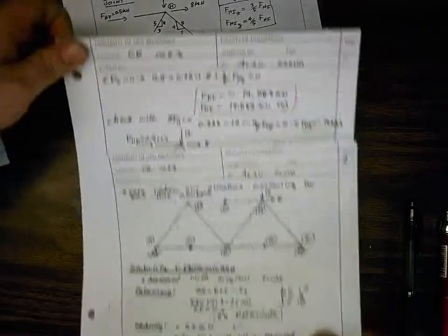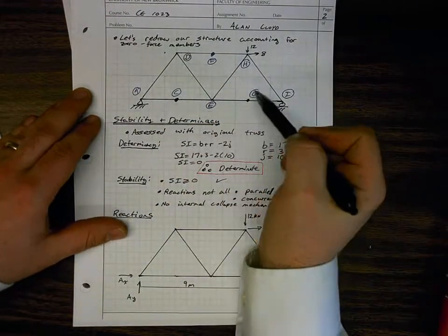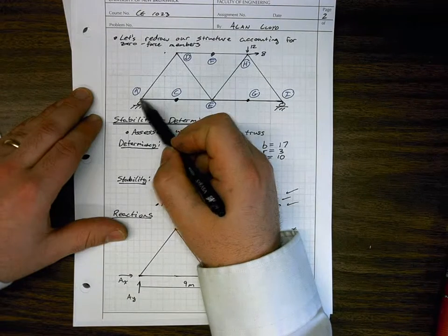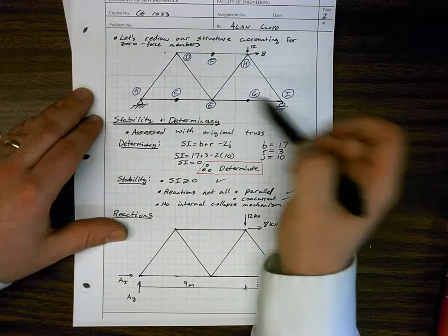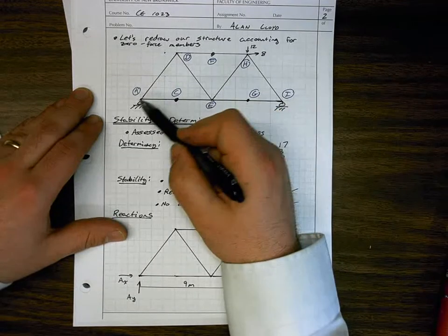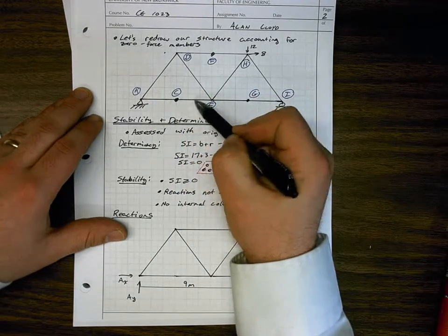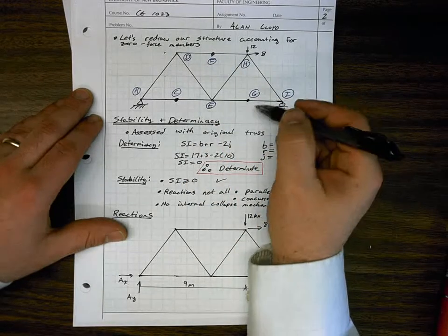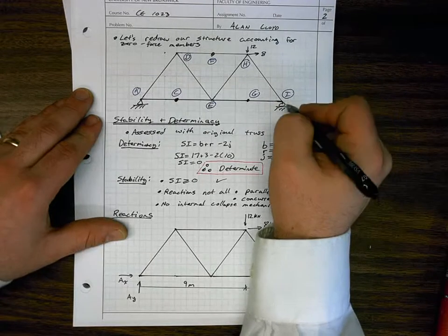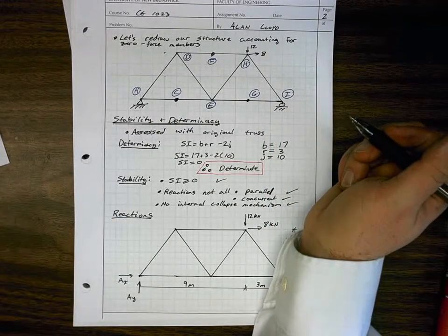If we go back and look at our structure, as we've identified we need to solve it, we've worked on joint A, joint D, joint E, and joint H. We also found the reactions. That allowed us to solve all of the member forces coming off of A. The member force at C we knew on either side, and F we knew on either side, and G we knew on either side. If we add up everything we know here, we find that we know every single quantity of this truss already. We don't need joint I.